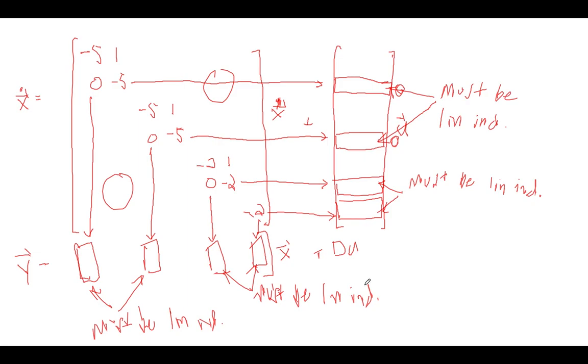So now let's say that this test failed and you said, oh, these two columns aren't linearly independent. What that would mean effectively is that you need to go back and add a new sensor. As you add a new sensor, you'd be adding a new row to your C matrix, and you'd want to add a sensor such that the number that appears in this position and this position are distinct from each other. So that new sensor lets you see these states differently than it sees these states.